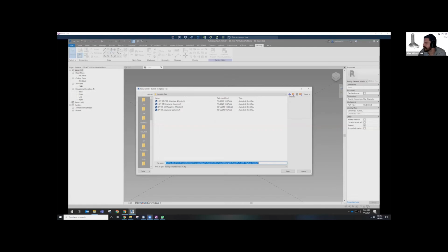Cool. So in terms of the workflow, the first part of the workflow is dividing the surface and getting the points to create the adaptive panels. One thing that's nice and fun is that Grasshopper respects the coding convention of the first number being 0. So you have 0, 1, 2, 3 as your point numbers. Adaptive panels does not use that convention. It uses 1 as the first number. So something to keep in mind is that if you look at your list within Grasshopper, the first point will be 0. If you're using adaptive panels, the first point will be 1.